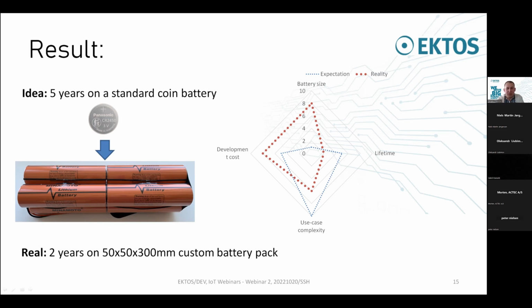We can, of course, add more battery, but as we know, it will increase the product cost, and we can reconsider the use cases. What we can do, we can transmit less data, we can measure with lower frequency, we can reconsider the communication technology, because, for example, GSM requires a huge battery, and Sigfox requires a small battery because of technology. So we will need to reconsider something.